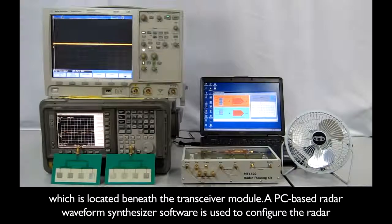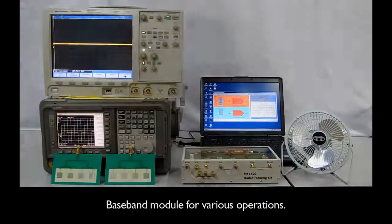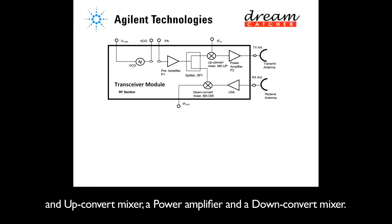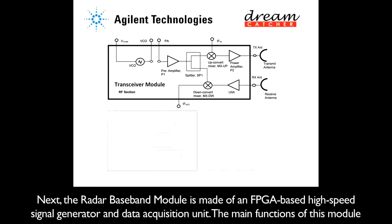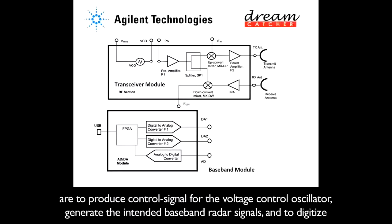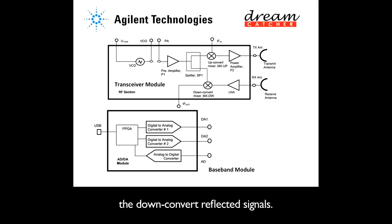A PC-based radar waveform synthesizer software is used to configure the radar baseband module for various operations. The radar transceiver module is a superheterodyne system consisting of a voltage control oscillator, an up-convert mixer, a power amplifier, and a down-convert mixer. Next, the radar baseband module is made of an FPGA-based high-speed signal generator and data acquisition unit. The main functions of this module are to produce control signal for the voltage control oscillator, generate the intended baseband radar signals, and digitize the down-converted reflected signals.